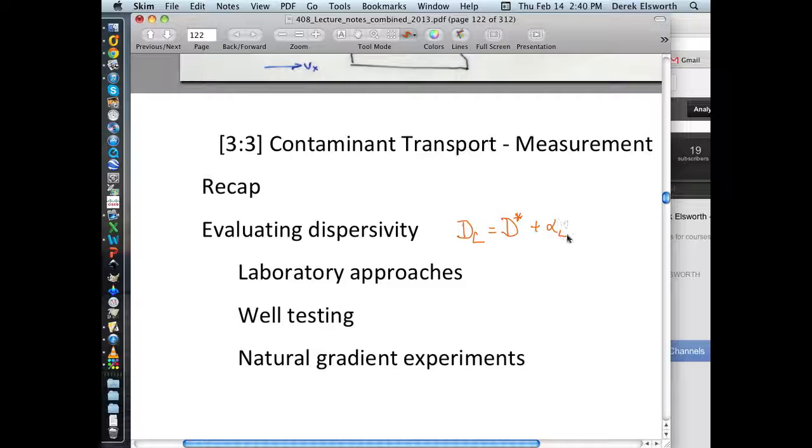A longitudinal dispersion coefficient multiplied by some advective velocity, typically along the direction of flow. And we can do the same for transverse dispersion. So two mechanisms, advection and diffusion. If we look at dispersion/diffusion, then there are two mechanisms embedded in that. One is molecular diffusion, very small, maybe 10 to the minus 9 meters squared a second. And another term, which we've already alluded to, is a function of the advective velocity, and also something that we've kind of said isn't a material property at all, which is kind of intriguing. So we'll get to that later on today.